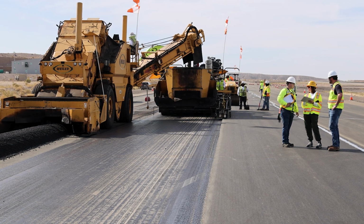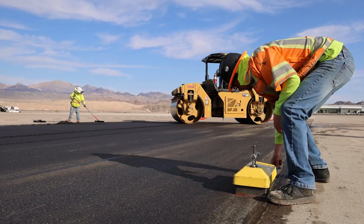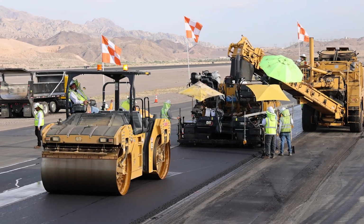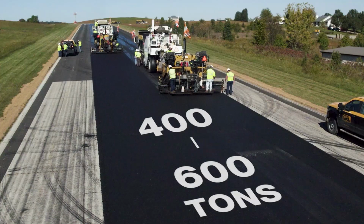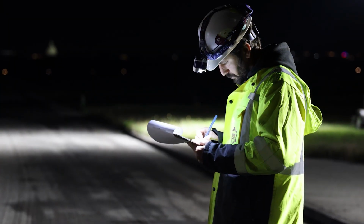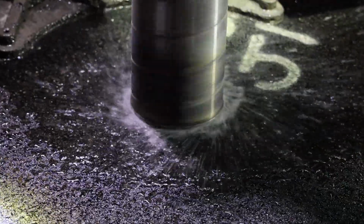A complete lot report details various aspects of the asphalt paving process for a specific section or lot. Project specifications dictate the size of each lot, which are generally 1 day's asphalt mix production divided into equal sublots of 400 to 600 tons. Airfield specifications typically require testing be conducted daily, per lot or per sublot.